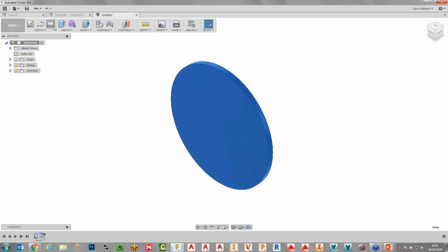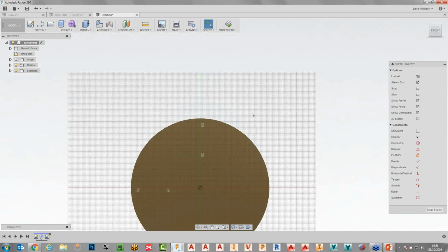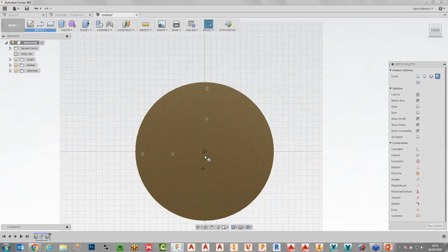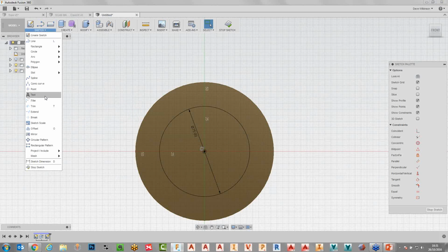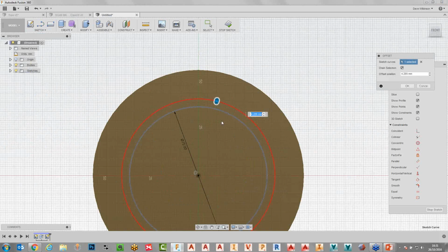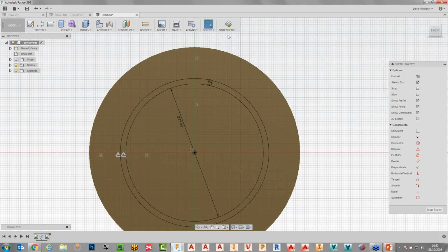just choose to create a sketch on that face there, and then add a little bit more detail, just the same as I did before. And this time we're going to choose a different dimension, obviously. And we're going to say we want a wall thickness rather than specifying a particular diameter. So if I zoom in a little bit, you should be able to see what's happening here. I want a wall thickness of say 3 millimeters on this.